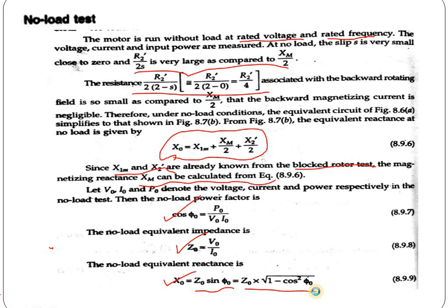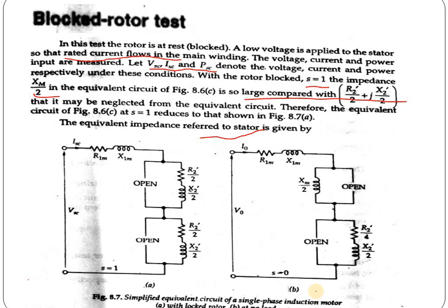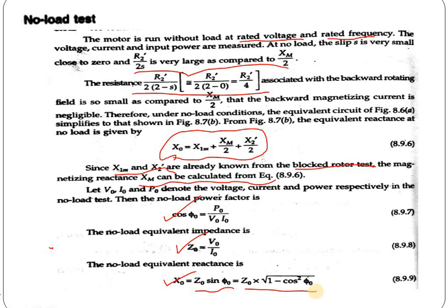So from the blocked rotor test and no load test, we have calculated all the parameters related to the single phase induction motor equivalent circuit, and this test is very important for knowing the performance of the single phase induction motor. The motor should be tested before its operation, and this test can also determine the losses of the induction motor.